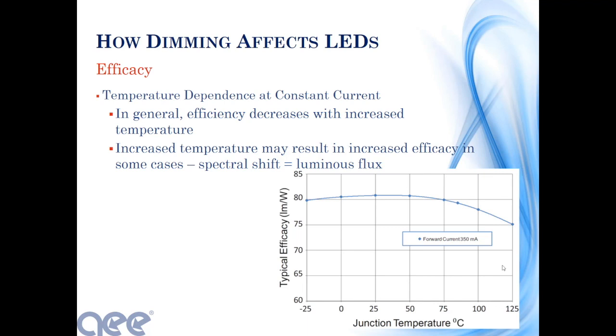It's not 45, which is now the federal minimum for general service lamps. So LED luminaires right now, 150 lumens per watt is, I won't say typical. That's some of the ranges for the DesignLights Consortium. But when you get to the LED itself, you can have an LED that's 180 lumens per watt easy. It's really the optics that determine how much light you get out of an actual luminaire. So we're talking about how much light we get out for the same power, basically.